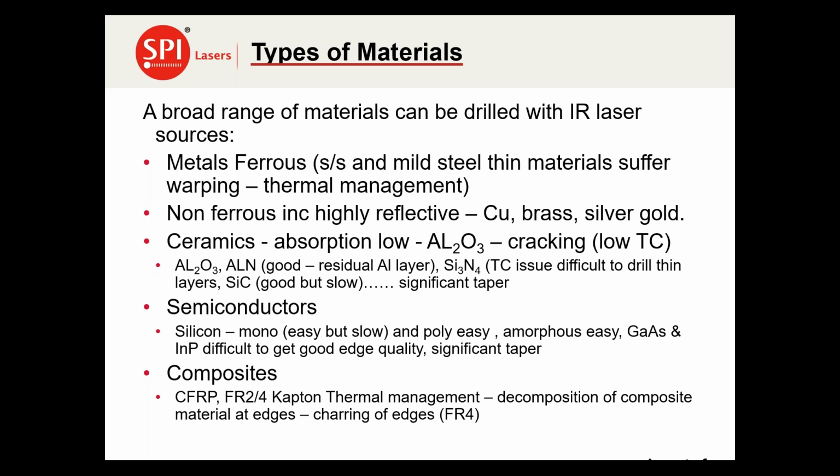They don't conduct the heat away very well, and parts, if you have particularly high densities of holes, tend to warp. So thermal management is very important. Non-ferrous metals, such as the highly reflective materials, copper, brass, silvers, golds, again, all can be drilled, and to some extent, the thermal issues are different. However, reflectivity and conductivity can limit the amount of processing you can do on these materials.